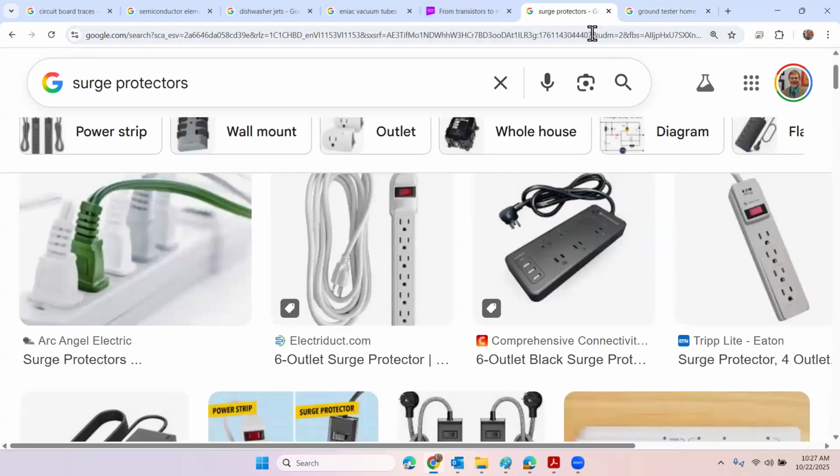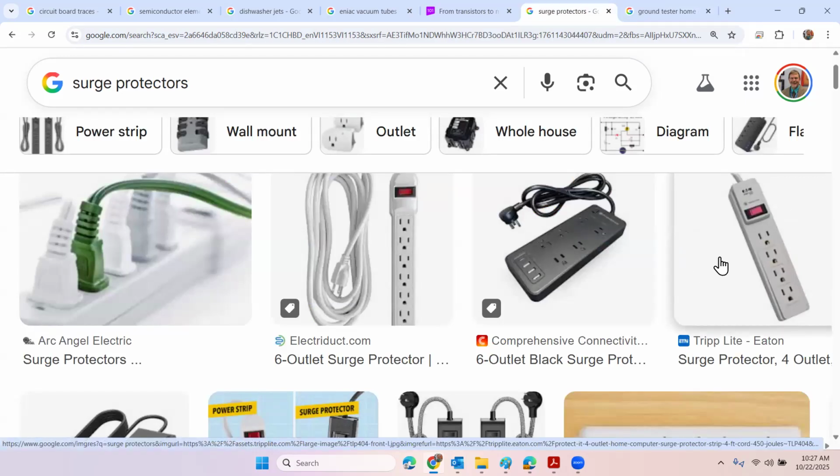When you have excess electricity, this thing cuts off the excess, but where does it go? You have extra electricity. What do you do with it? The surge protector is capable of protecting your equipment if and only if there's a proper ground. The excess current is redirected and taken out by the ground.